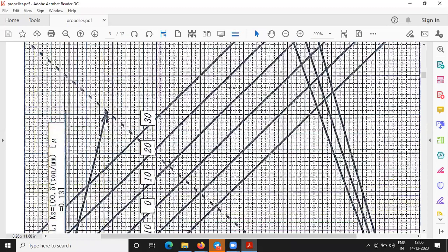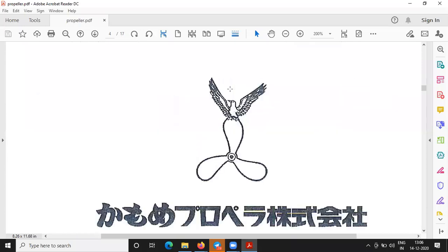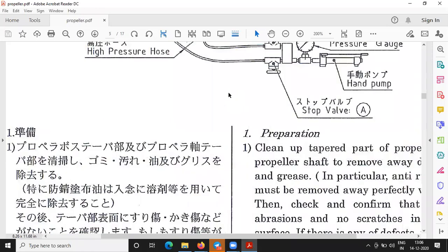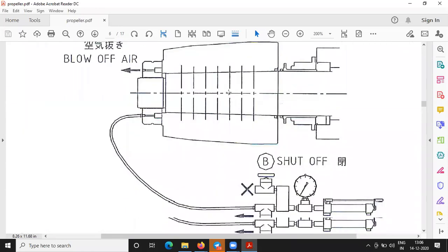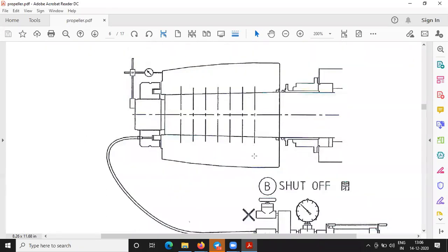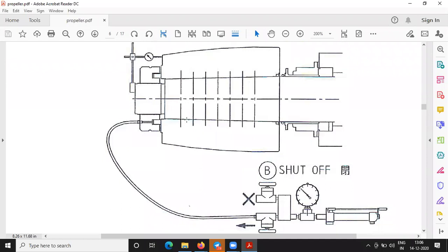So what is the pressure that you give in the hydraulic jacks? 1200, 1100? Yes or no? That pressure you give in the hydraulic jacks does not tell that that is the limitation of the material. That is the limitation of the stud which you are elongating. Following my point?